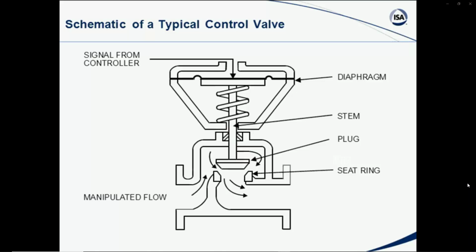And again, the selection of a control valve for each application is basically very unique, very individualistic, because each valve is selected based on service, the type of material, the corrosivity, the erosivity of the materials. You have to select not only the body materials, but the materials for the trim, and that could be a source of questions that I would encourage you to have a material selection guide with you on the exam.